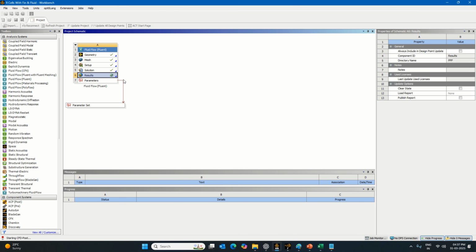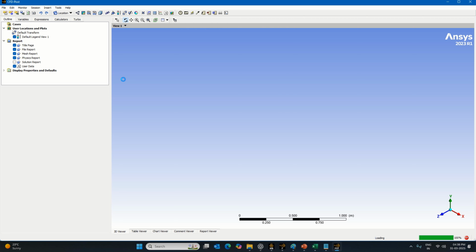Okay, the last part is related to results. Just go to Edit. Now we'll see how to generate a simulation video of this with temperature, streamline, or the volume rendering which we have, so that we are going to visualize it now. First of all, a blank window will appear when you open the results part for the first time.